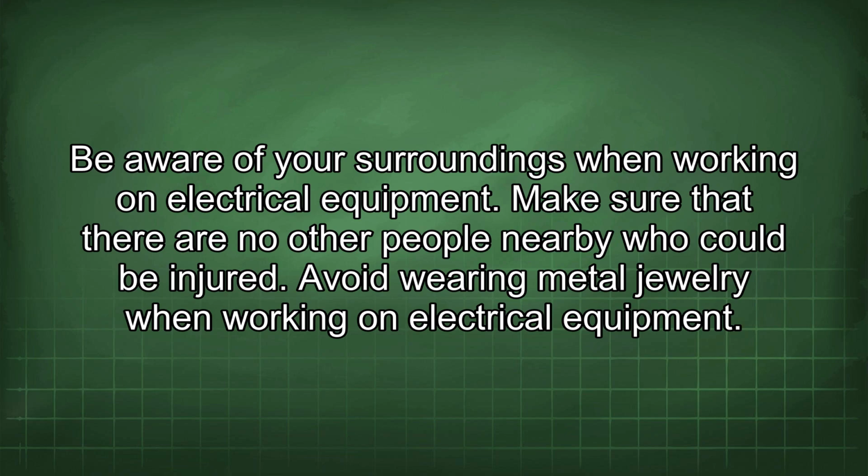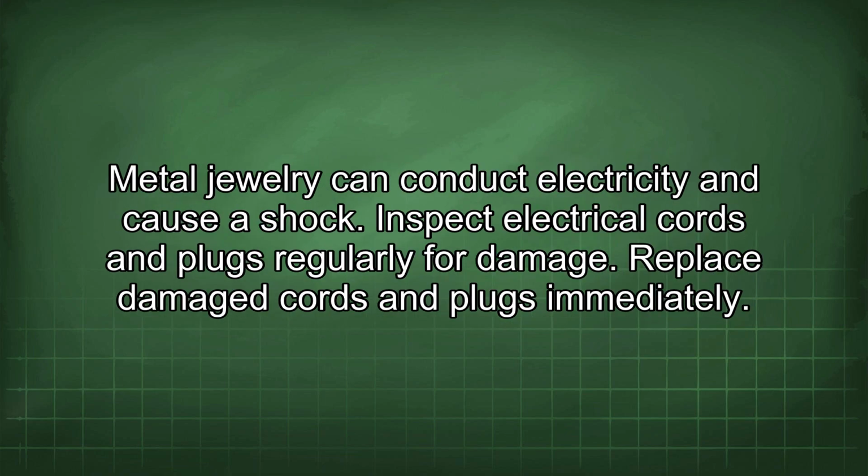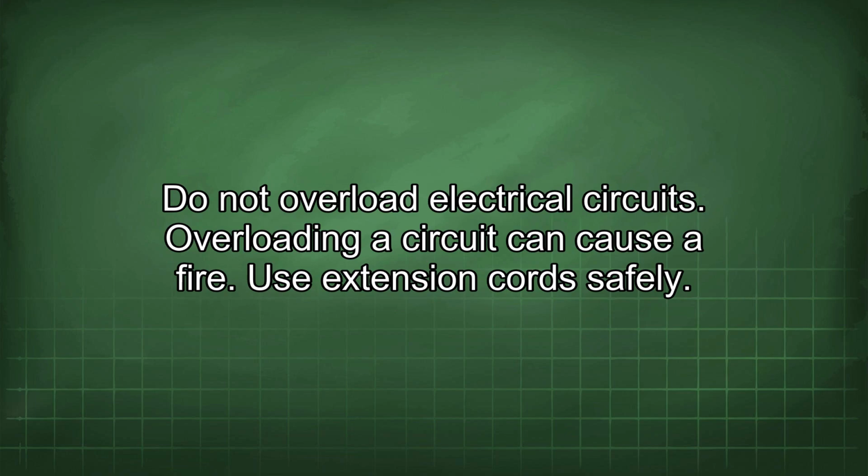Avoid wearing metal jewelry when working on electrical equipment. Metal jewelry can conduct electricity and cause a shock. Inspect electrical cords and plugs regularly for damage. Replace damaged cords and plugs immediately. Do not overload electrical circuits. Overloading a circuit can cause a fire.